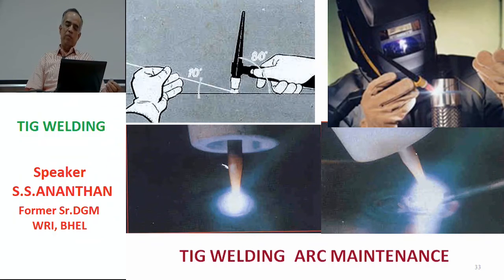We give this 80 degrees because the welder has to have a view of this molten pool for proper control. So this slight inclination is given according to the requirement of the welder. And the 10 degrees is given so that the filler wire is continuously fed into the molten pool. We keep as low an angle as possible. That is the logic on which the whole thing is working.